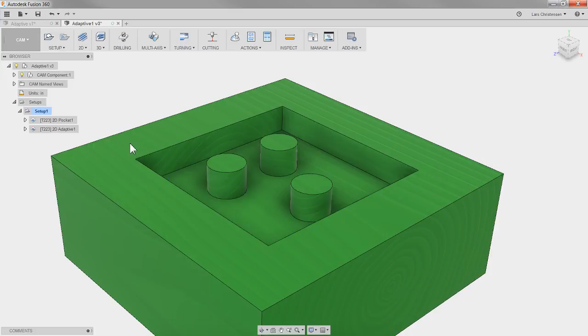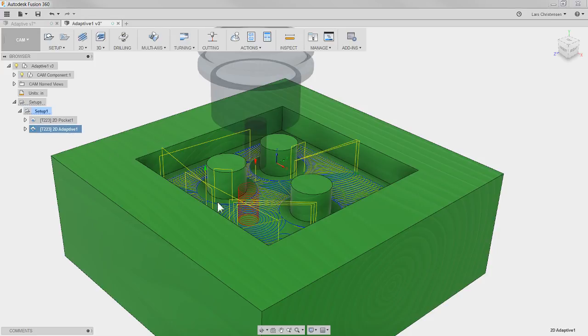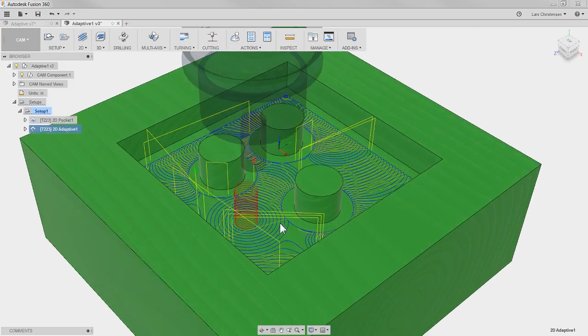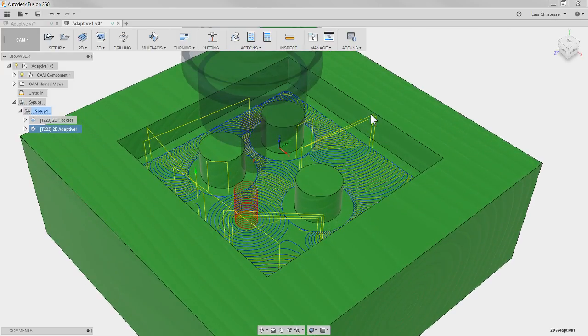So again, I'm using the default settings inside of Adaptive. I just applied this tool path out of the blue. I went in, I selected the same tool, I selected this area to be machined, and I hit OK. We played with optimal load, sorry. So some of the things that we got to talk a little bit about is, one of the first things you get, these rapid moves, right? You see all these rapid moves in here.